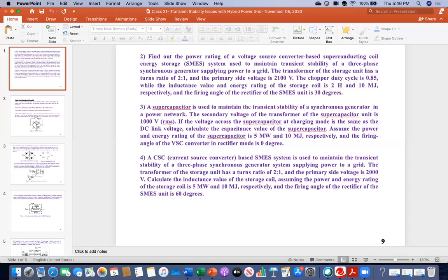Is it 3000? The capacitor value? No, VDC. 1350.47. Okay, I made a mistake. I said 3 times root 2 times 1000 divided by pi, and cosine 0 is 1.